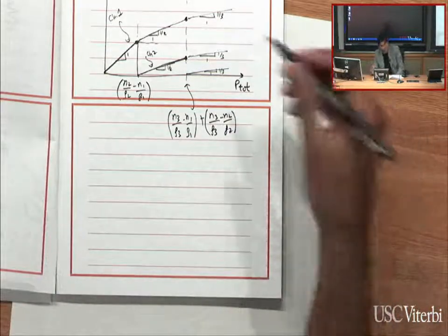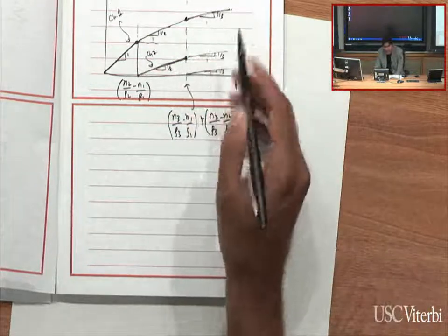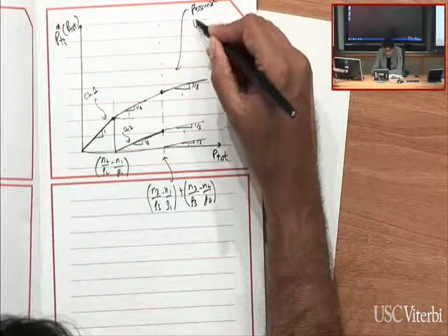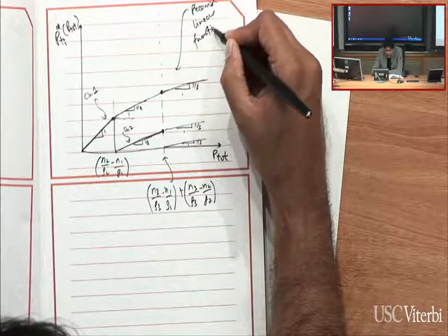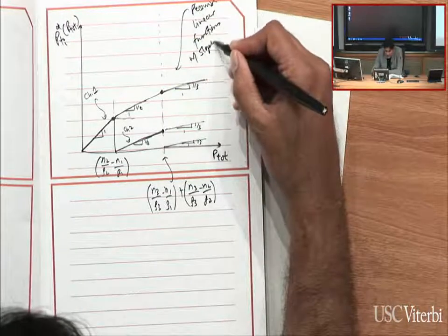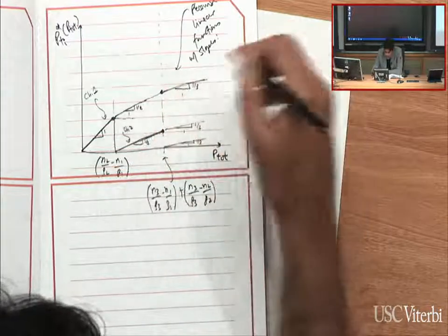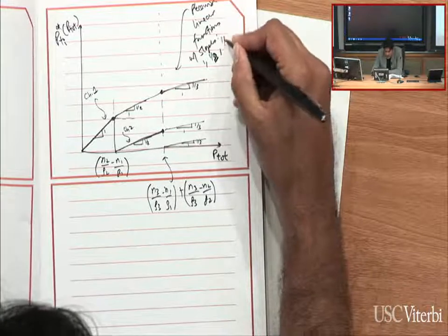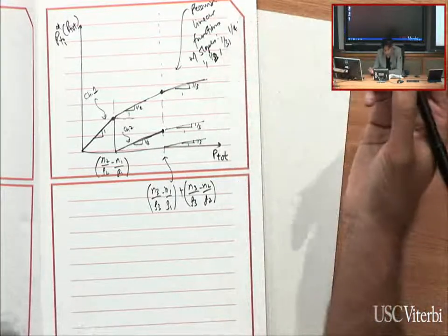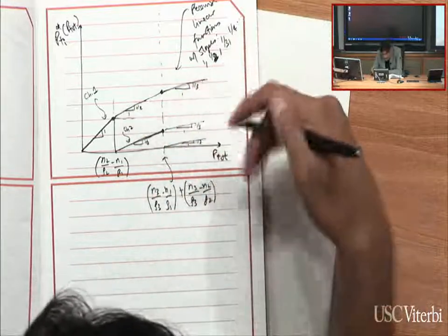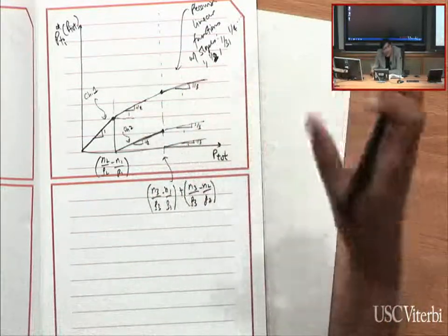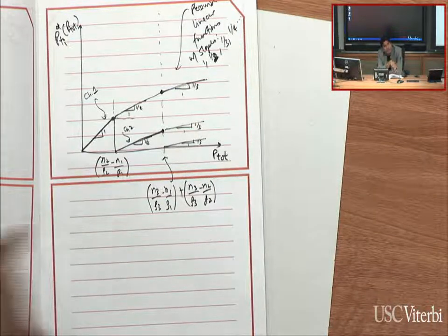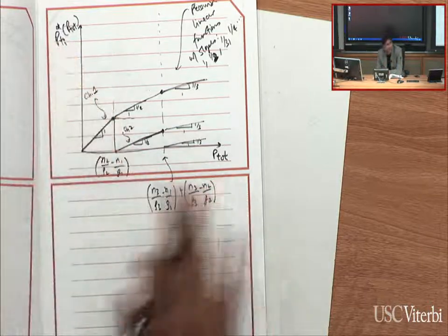And so on. If you plot these functions, they are piecewise linear functions with slopes depending on which channel it is, the best channel, the second best channel, and so on. But their slopes keep decreasing, 1/2, 1/3, 1/4, and so on. The points at which they start to switch are defined by the gaps between their noise values. So if you were to solve the equation we saw before and graphically plot how much power each channel should receive as a function of the total power, it would look something like this.